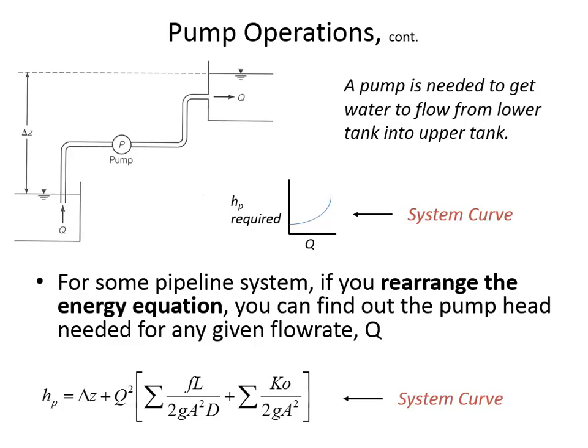L is just going to be the pipe length between the origin and the destination. And even if it's submerged pipe length, you still have to account for the entire length of pipe, because even a submerged pipe induces friction. So, these two pipe lengths, even though they're submerged, the water comes in here and goes out there. And so if the entire length is 50, that's what you've got to use as the entire length.